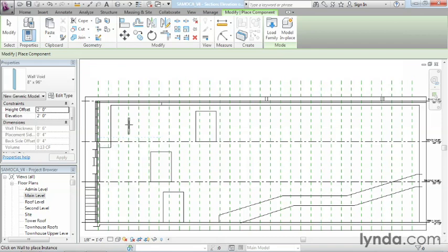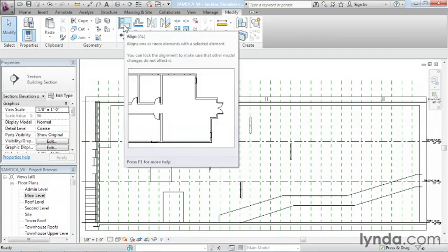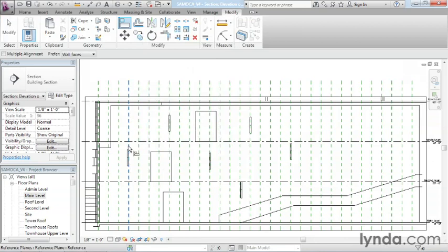And you can kind of see that you can place this really anywhere you want to go. What you do is you sort of place it nearby these grid lines. Maybe I could place a few of them like over here and over here and over here. And then after you've done however many you want of this size, and again, avoid this area here where the stairs are, you cancel out of there, you go to the Modify tab, and you use your Align tool, and you just align from the reference plane to the center of the void.